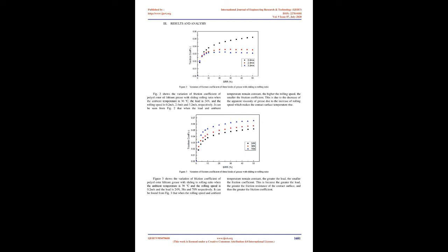Before the temperature control box reaches the set temperature, the ball and disc idle at the speed of 1 m/s. When the set temperature is reached, the rear end of the driving rod of the experimental ball is lifted to apply load on the contact point of the ball and disc. When the set load is reached, the ball and disc will rotate at the set speed, and by increasing U2 to reduce U1, the ball and disc slide between them.